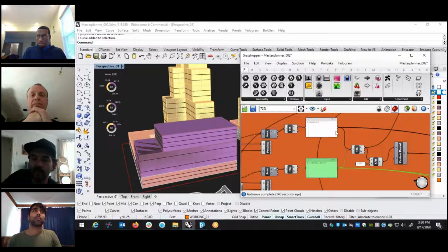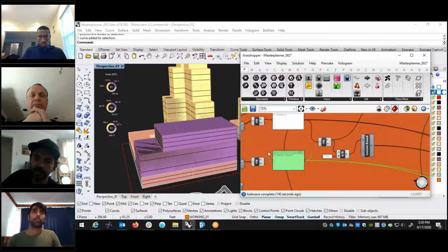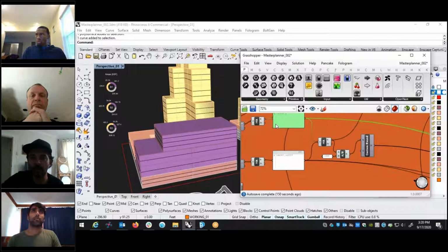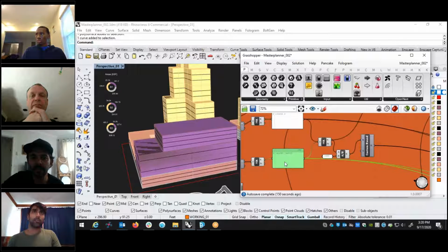Okay. Now I have area from Office 1, area from Office 2. These are what's called a panel, right? So if you're going to double click in space and type panel, great way to triple check your work. I add them in many scripts just so, again, I can see the output, make sure it's making sense, or I can double check my math.